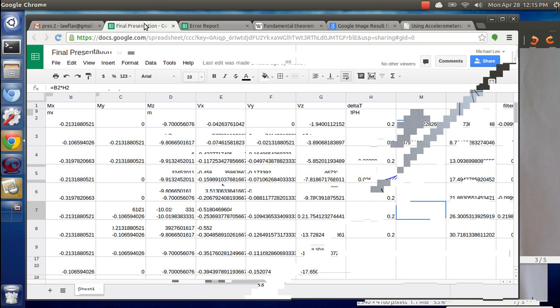That is called noise. To filter out that noise, I'm taking this average. For any given spot, I'm using the average of the previous 5 to filter out if one of those was a spike or a big dip. Hopefully that would smooth it out so I could get a better result.